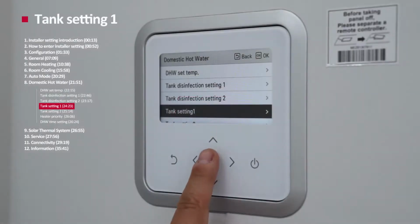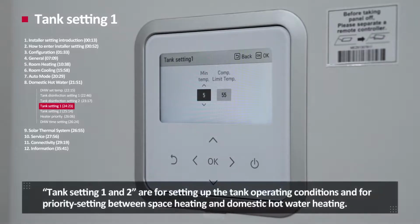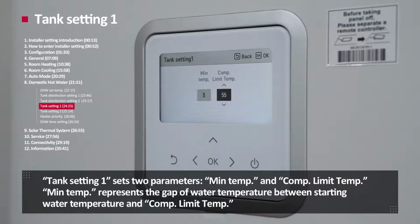Tank setting 1. Tank setting 1 and 2 are for setting up the tank operation condition and for priority setting between space heating and domestic hot water heating. Tank setting 1 sets 2 parameters: minimum temperature and comp limit temperature. Minimum temperature represents the gap of water temperature between starting water temperature and comp limit temperature.